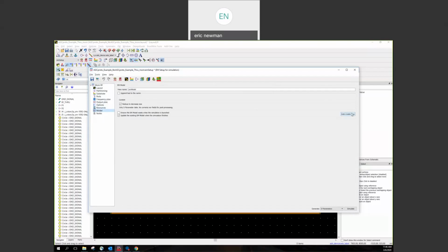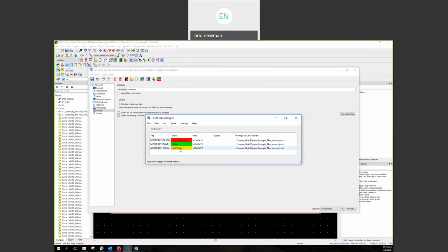It can be important to go ahead and create yourself an EM symbol, so that later on you can access that. And if you want to start doing sweeps, you can build a database of different EM models within. Anyways, we'll let that go. I could click simulate right now, but first I always like to encourage people to look at the 3D EM preview of your design. You click on this green cube here. It might take a little bit for it to launch. You can look at the cog down here and see that this thing's running. It's actually rendering a graphic at this stage.